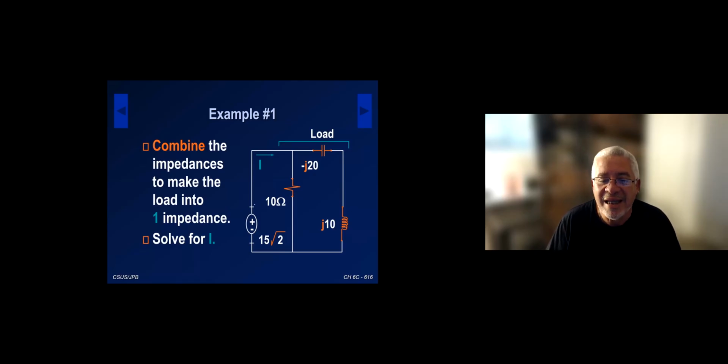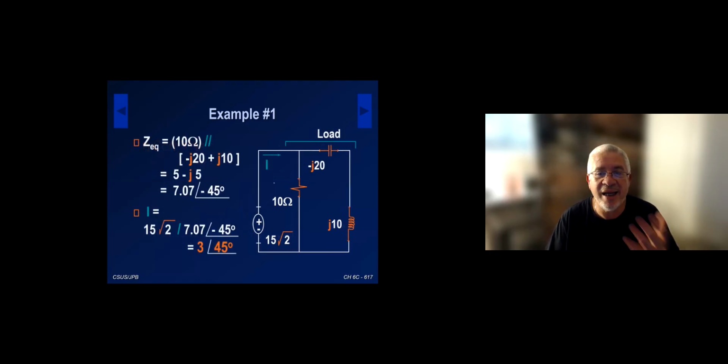If I focus on this source, I have the voltage; all I need is the current. If I have the current, I can answer the complex power question, 1/2 phasor voltage times phasor current conjugate. I can combine the impedances, just complex resistances, that's the nice feature of phasors. So the 10 ohm is in parallel with the series combination of the capacitor and the inductor impedance.